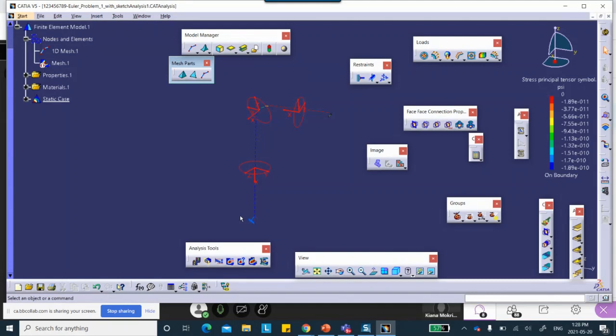At what location? Exactly. In other words, give me the stress at the top fiber, at the bottom fiber, halfway in the middle, at the center. So to expect CATIA to give you stress is foolish, because before there was no issue when we were doing it with solid elements, you could find the stress anywhere. But here, you have to say where.